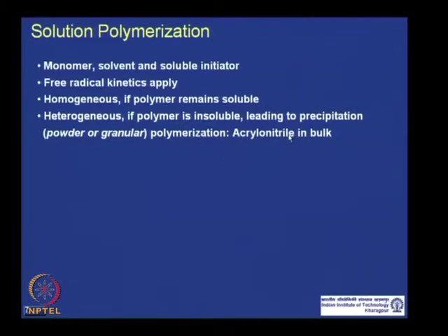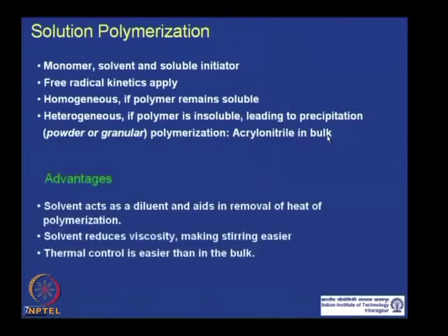For example, acrylonitrile in water. If you start polymerization of acrylonitrile in water, polyacrylonitrile is not soluble in water, so it precipitates out. So, you get polyacrylonitrile powder or granules. Obviously, the disadvantages you had for bulk polymerization, in this case you do not have those problems, because you are doing it in a solution, so heat transfer can take place efficiently, because in a solution viscosity does not build up.